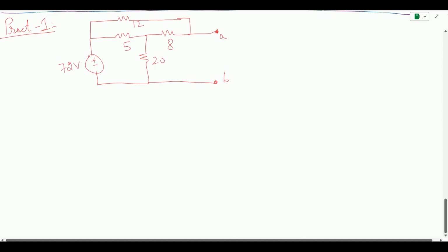You need to find the Thevenin equivalent for this. Okay, just to give you a starting point, you can apply the node voltage method, because we know that the Thevenin voltage depends upon the open circuit condition, which is over here VAB. So VAB is going to appear across this point over here. So whatever is the voltage appearing at the 20 ohm, it is going to be your Thevenin. In order to apply node voltage, you can have essential nodes at this point, and even this point, and then you have the common ground over here.